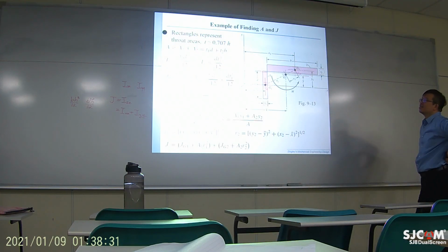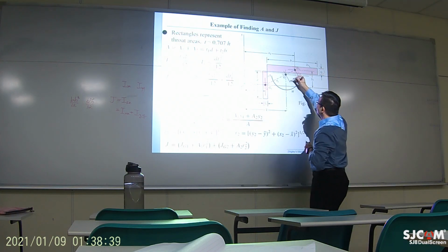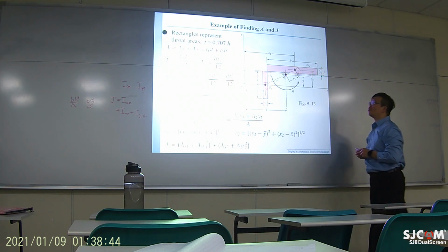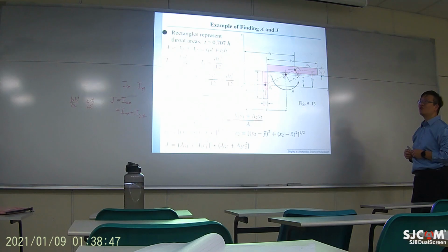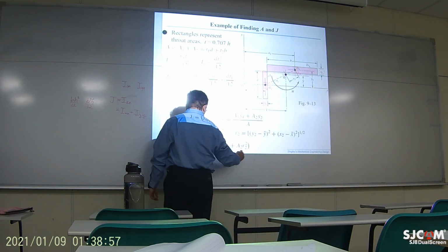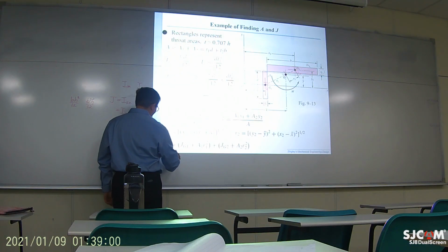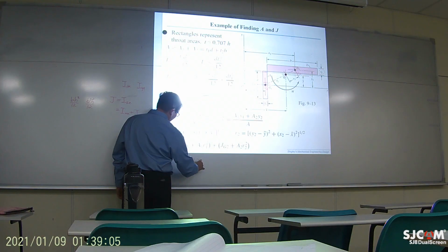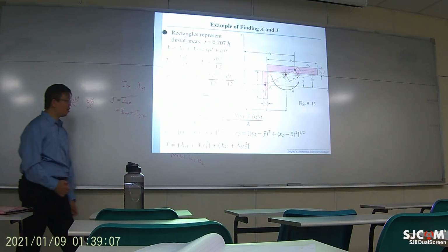It's not the polar moment of inertia about the rotational center. So we then need to compute the total polar moment of inertia about G. So how do we do that? Using this equation. It's the parallel axis theorem. Okay, parallel axis theorem.